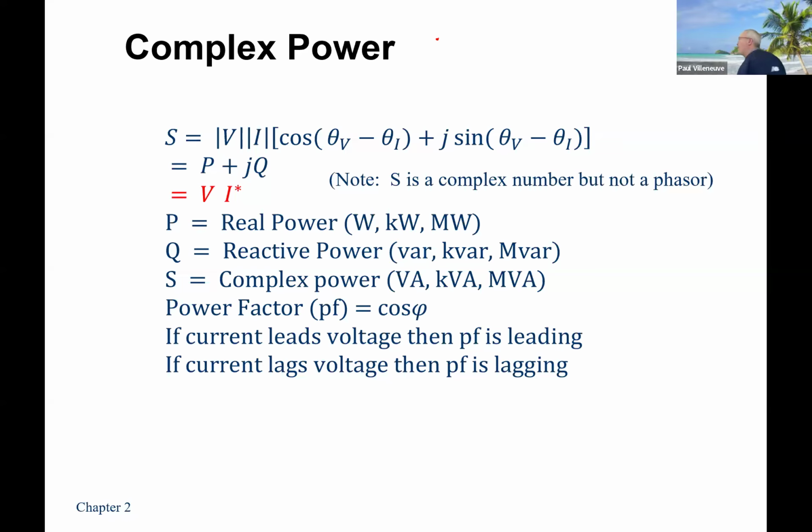So we're going to rewrite these two terms as the S term, which is now going to be our total or apparent power, a combination of the real power plus this reactive power, that borrowed power that has to get sent back. And that's P plus jQ. I also can call it V times the conjugate of I. Why do I put the conjugate of I in there?